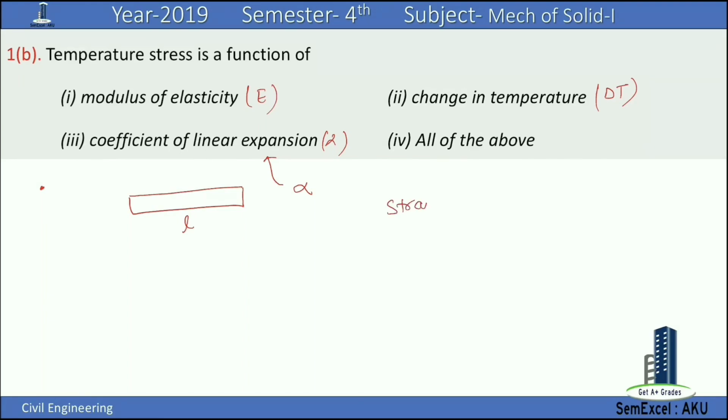Then the strain is defined as alpha into delta T, and from the Hooke's law we know that stress is directly proportional to the strain, or stress is equal to Young's modulus of elasticity into strain.